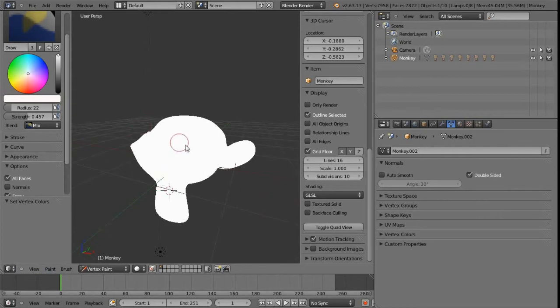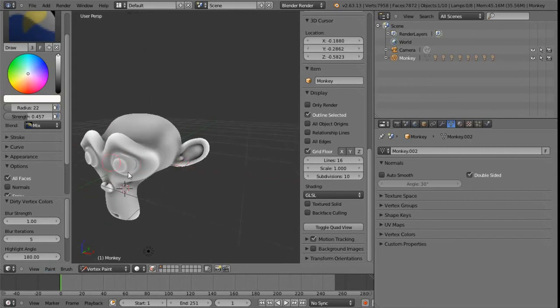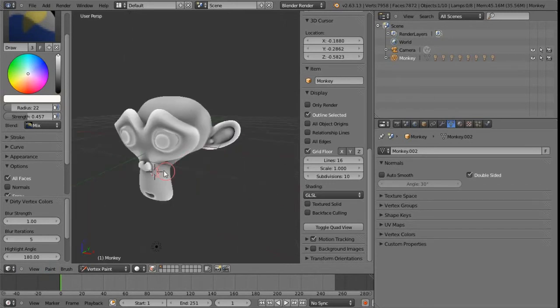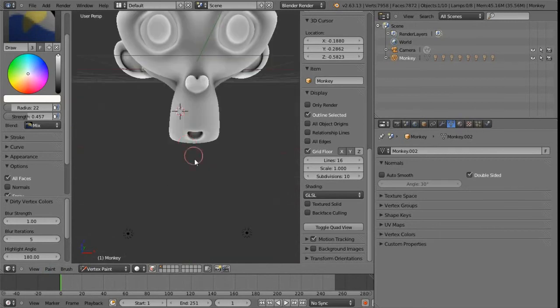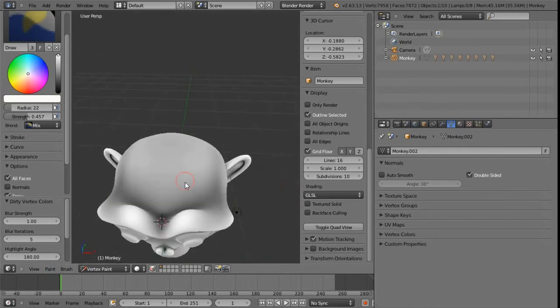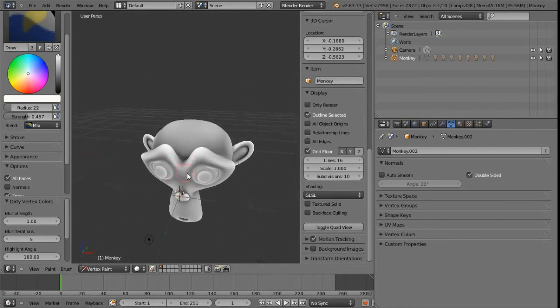So to do an ambient occlusion bake into the vertices, what it's called in Blender is dirty vertex colors for some reason. So we just click on that there, and we can see that's taken effect. It's given it a bit of an occlusion bake, so many of the sections which you might expect to be in a natural shadow, we can see that all the recessed and slightly occluded areas are darker. So we can see that that's basically giving us this kind of a look.